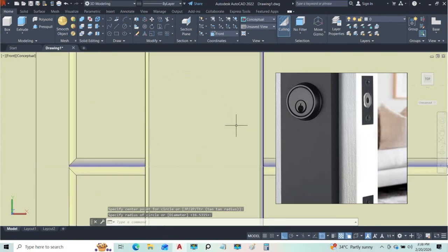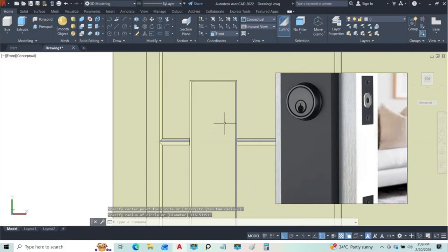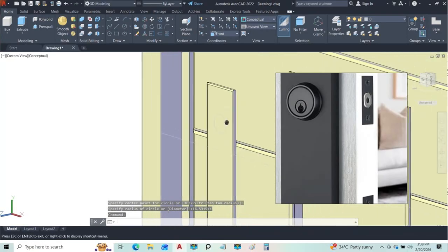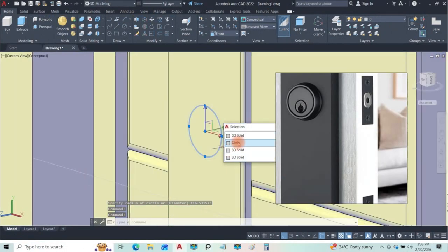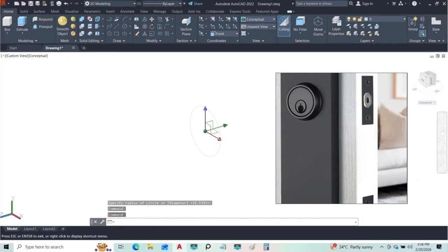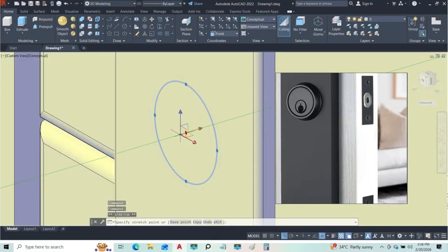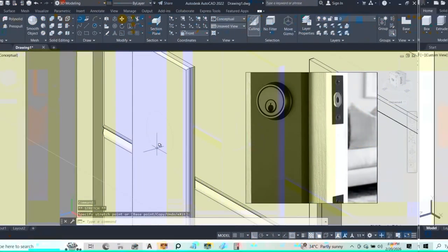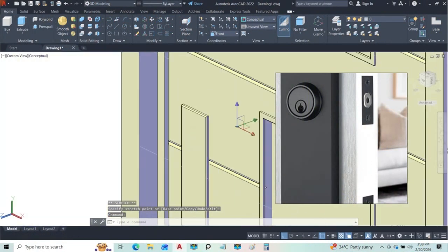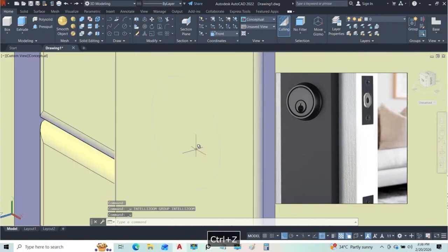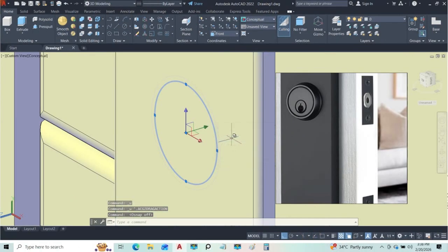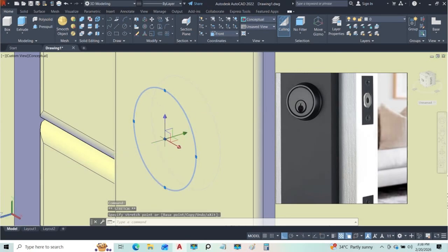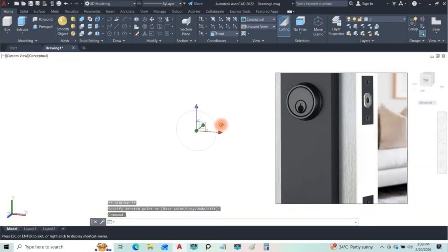I can see, I don't know if you can see, these are the 2 circles. So for this one, I'm selecting this inner circle, which is a smaller one. I'll move it a little bit out, and you notice something. I'm going to undo that operation till I have both, and then I'll turn off my snap. The reason is because it went to snap backwards, so I'll just move it all by myself without any snap. So we have that.